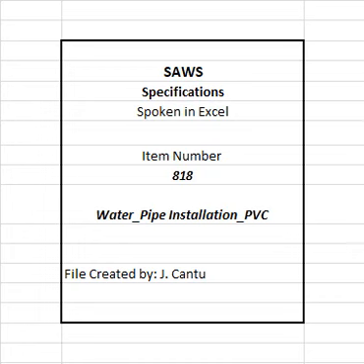10. PVC pipe markings shall include: A. Manufacturer's name or trademark. B. Standard to which it conforms. C. Pipe size. D. Material designation code. E. Pressure rating. F. SDR number or schedule number. G. Potable water laboratory seal or mark attesting to suitability for potable water. H. A certifier's mark may be added, and I. Manufactured date; installation shall not exceed 1 year from this date.